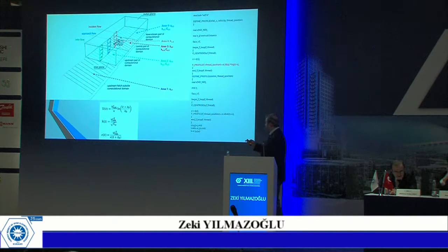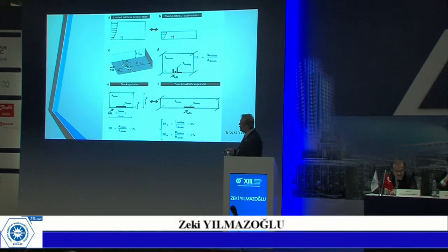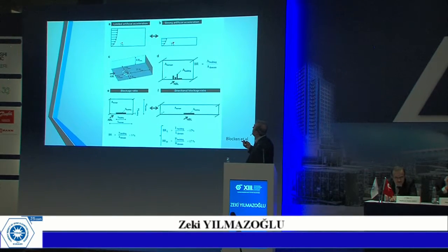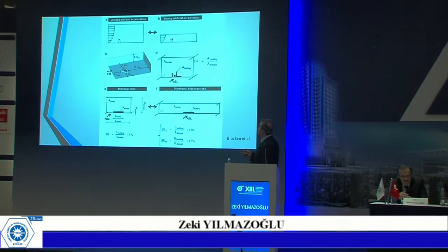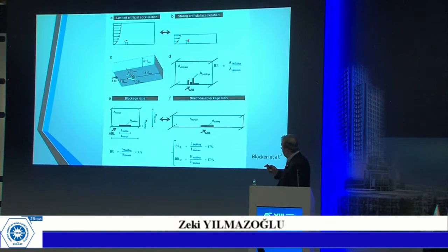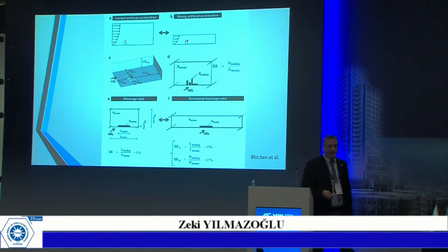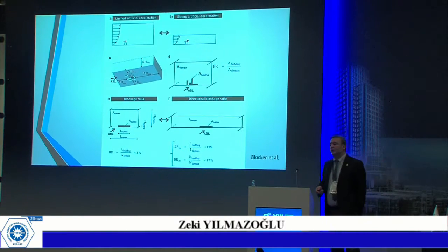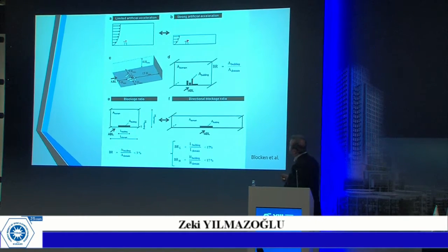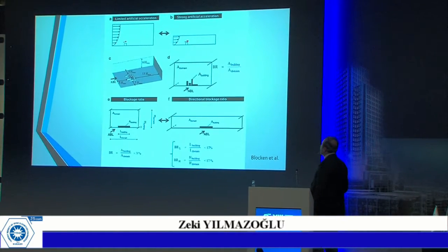And the dimension of the enclosure has great importance in our solutions because of artificial acceleration of the air inside the enclosure. The blockage ratio, wind tunnel experts know the blockage ratio, the same is used in numerical simulations. And after these calculations, the dimension of the enclosure is found.